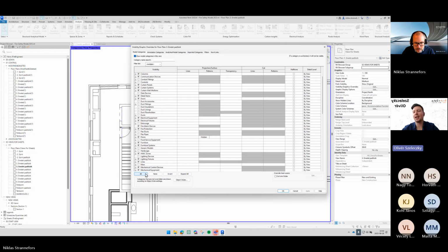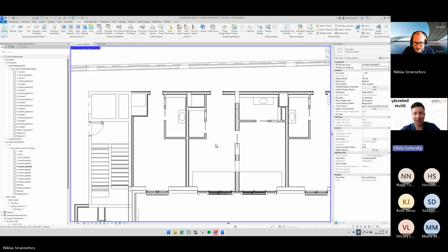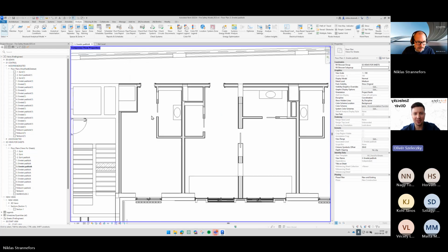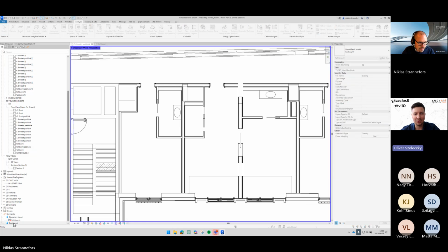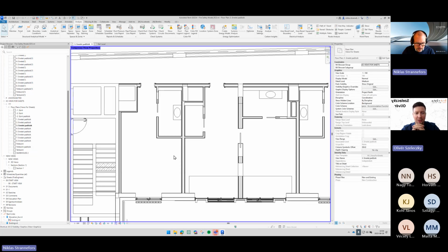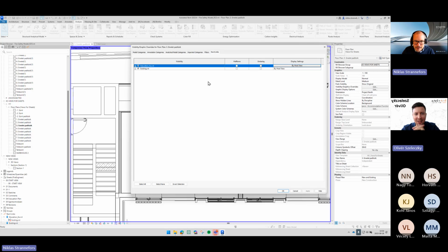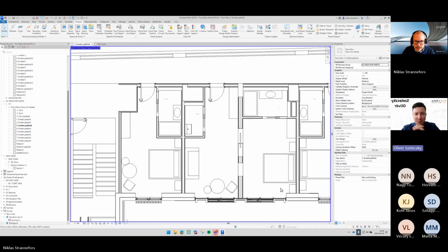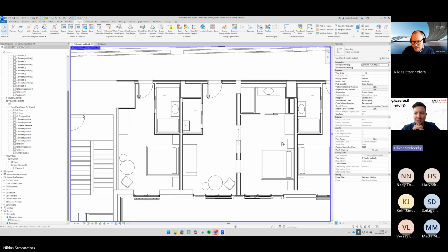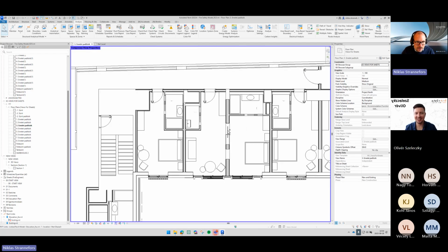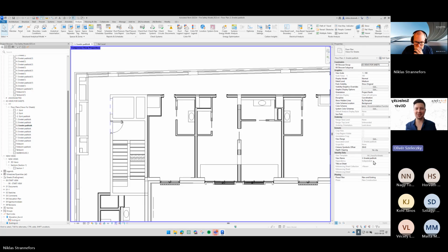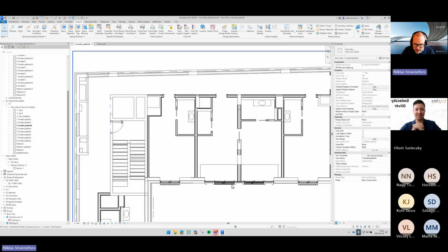Actually, oh, I know what it is. Can you go to your Revit links, please? No, sorry, just in the visibility graphics. Yeah, here. Just for the fun of it, can we turn off the structural model? Just press OK. Okay, so there's a generic model in the structural model that is in the way. But the strange thing is...